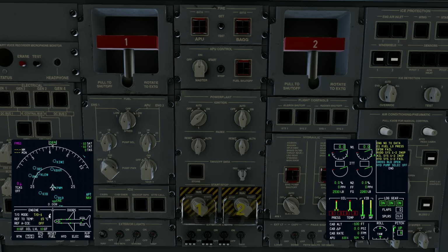We have two thrust ratings on this aircraft. We modeled the Embraer 145 with the A1 engines, and it comes with two thrust ratings. It has TO1 and Alt TO1. TO1 is your maximum thrust takeoff. So when you select TO1, you're telling the computer, I want the maximum thrust possible for you to generate under these conditions. And it's not just looking at the engine itself, it's actually looking at the pneumatics panel. So it will kick off the packs when the temperature is above 19 Celsius as well to help generate that maximum thrust. So it has full control over the things that contribute to engine performance.